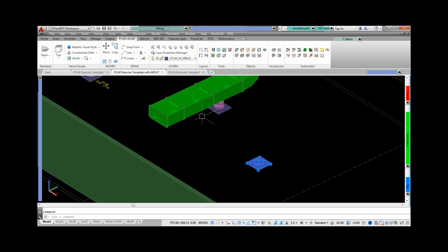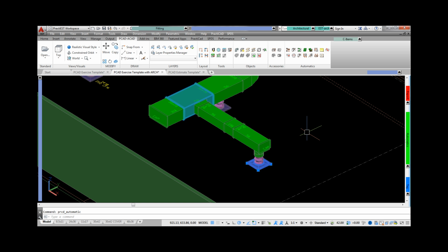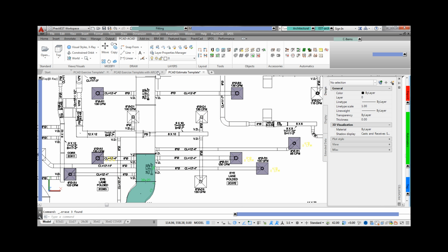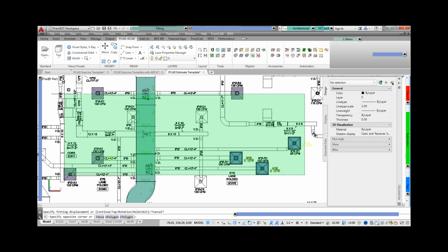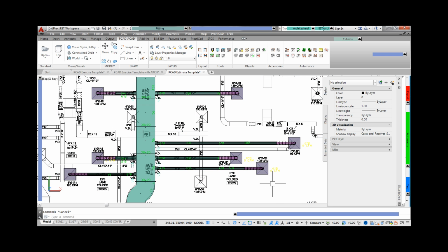All the parameters you need are there, including min, max, flex lengths. Here's a route that requires a boot tap first. It runs over a grill's neck, then it stops, end caps the run, and then drops down to connect with a spin collar and flex. Using the auto routing feature can truly save a draftsman a lot of time, and it's great for estimating as well. Using PractiCAD's estimating features, we draw over the PDF. You can see here the job requires conicals, pipe, and flex. We window the area and route as we need.